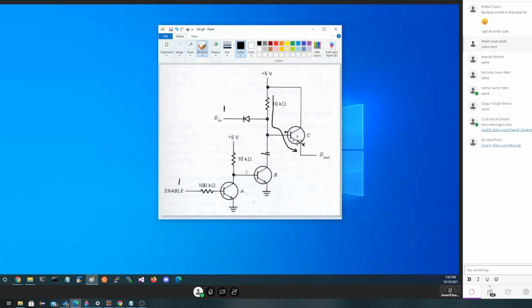If the transistor is turned on, what happens to the collector emitter? Somebody raise your hand, tell me in a transistor that's fully saturated and turned on, what happens to the collector and the emitter? Robert? Electricity flows through the collector and out the emitter. Yeah, but what's the difference in their voltages? I'd have to look back at my notes. Saturated transistor, what's VCE? What are we planning for, Scott? It's going to be very minimal, like 0.1 volts. Right. Call it zero.